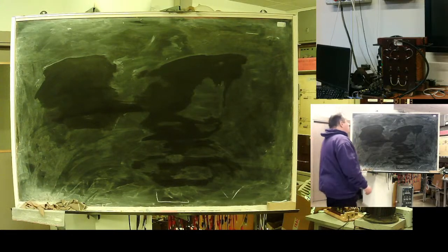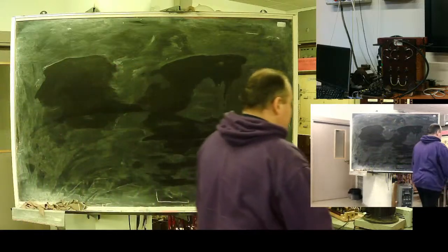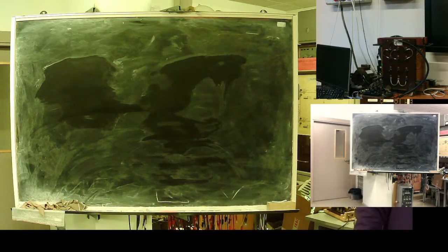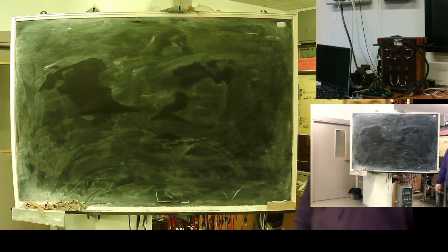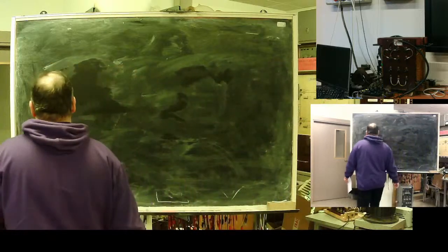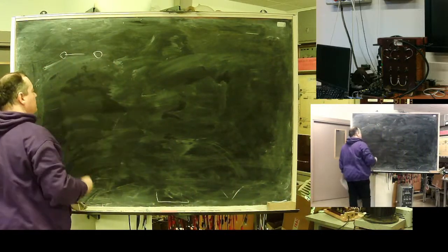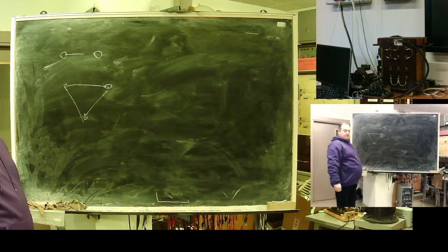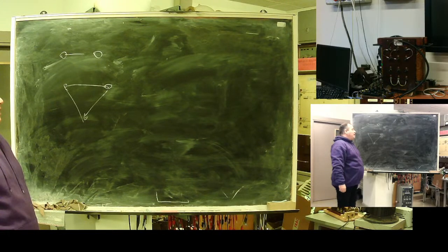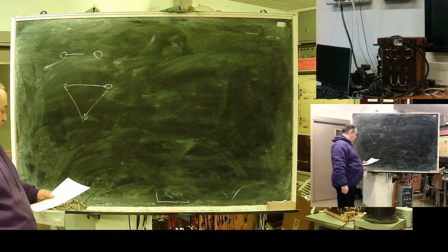One more, usually one single wire is used for up to, in theory, up to 500 square millimeters. For higher current densities, it's not practical to use a single wire. And split wires are used. Starting from 2-wire system, split by 3, by 5, up. I saw a picture of 9 in one phase. Split system.